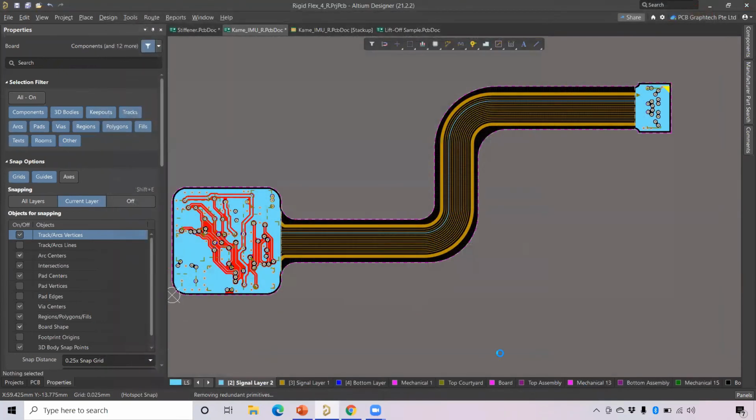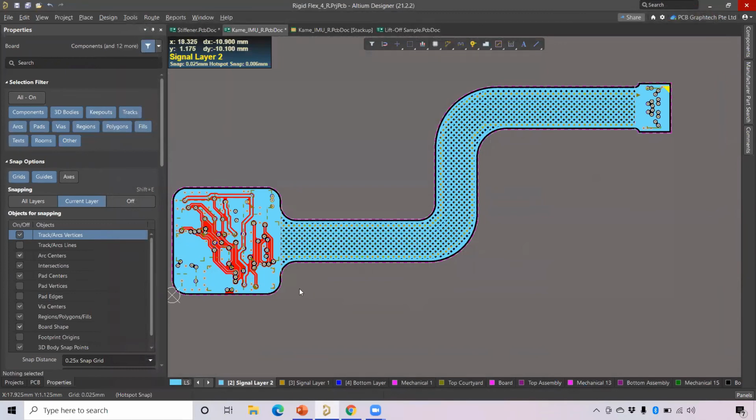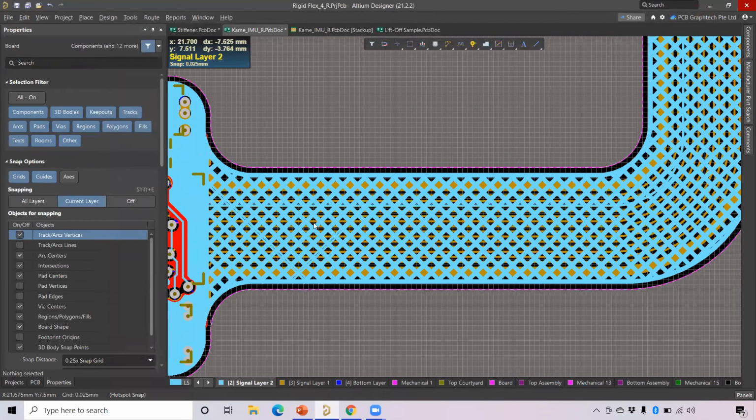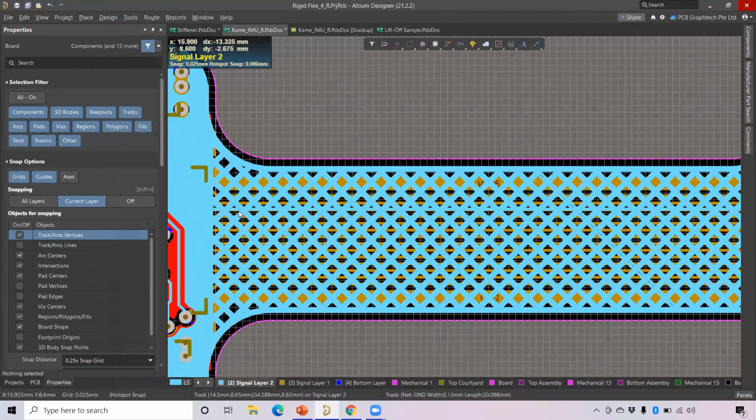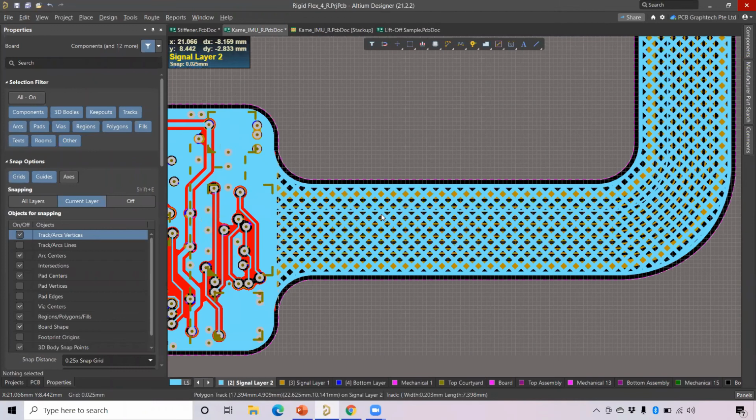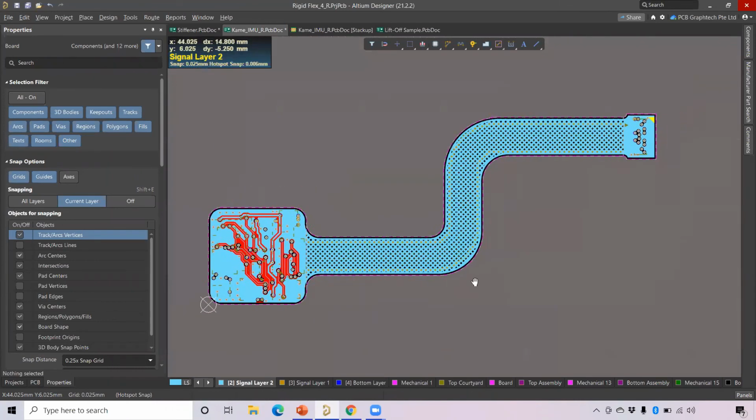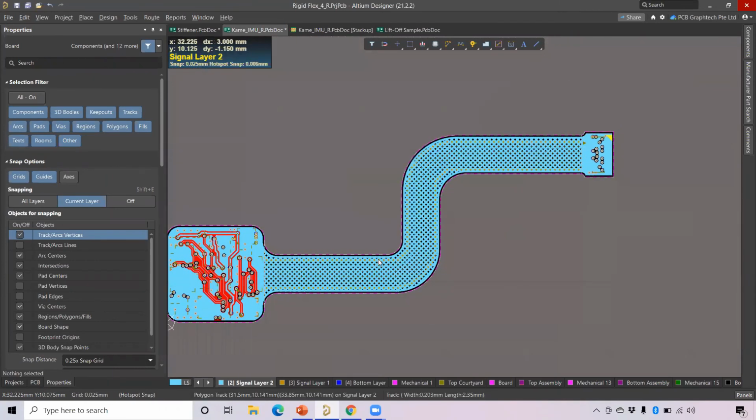So now you can see, I brought in my hatched copper, and below it there is the trace. This is the trace I placed in this layer to avoid the high-speed net problem, that is signal integrity problem, because it's a high-speed net. Sure, it will have the return path problem. So to avoid it, I place a solid copper in this layer behind that particular net. Okay, you can do this here. So this is how you can place your copper.